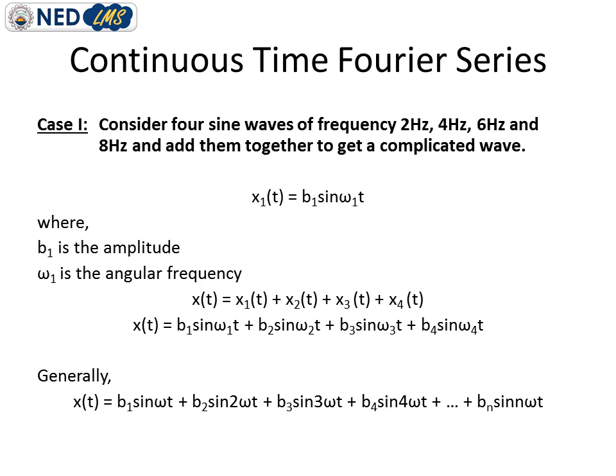The Fourier series states that any periodic complicated waveform can be represented as an infinite sum of sine and cosine waves. So we are representing the fundamental frequency and all other frequencies in relation to that fundamental frequency.